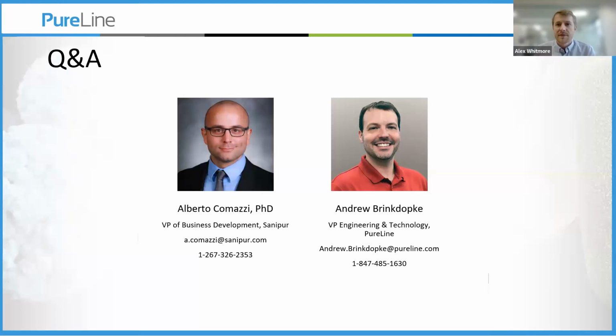Thanks, Alberto. Follow-up question was, can the systems be tied into a facility BMS system? I'll take this first, and then I'll let Andrew answer. Yes, I actually forgot to mention that during the presentation. The system can be tied to the BMS either through digital inputs or analog inputs, so 4 to 20 milliamp, either Modbus or BACnet. So either one.